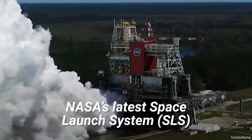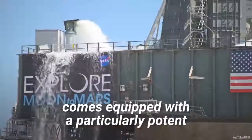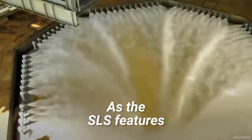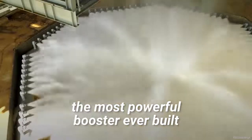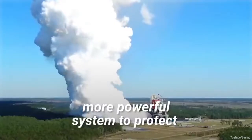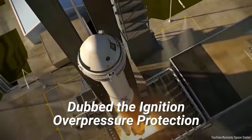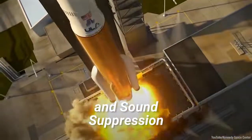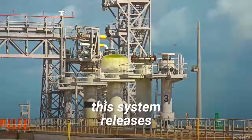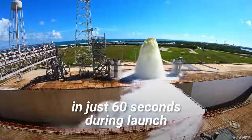NASA's latest space launch system for its Orion spacecraft comes equipped with a particularly potent sound suppression system to pair with its new rocket. As the SLS features the most powerful booster ever built, engineers saw fit to design a new, more powerful system to protect the equipment and crew on the ground. Dubbed the Ignition Overpressure Protection and Sound Suppression, or IOP/SS Water Deluge System. This system releases 450,000 gallons of water in just 60 seconds during launch.